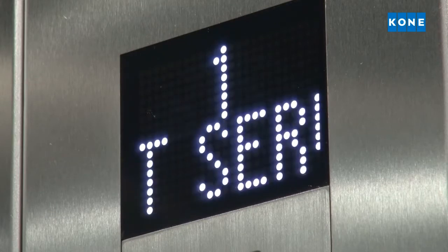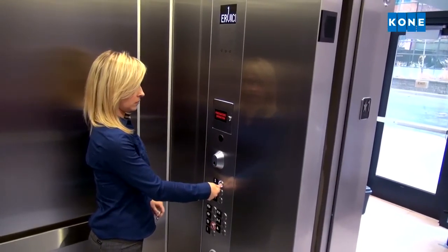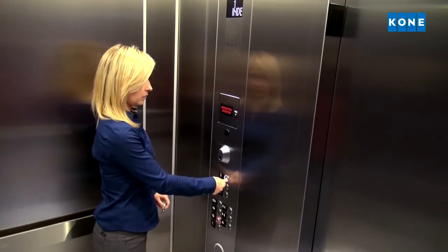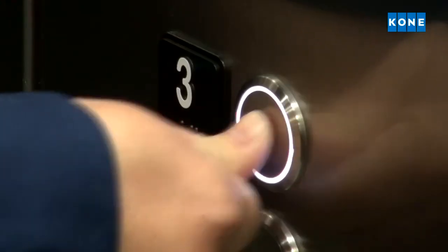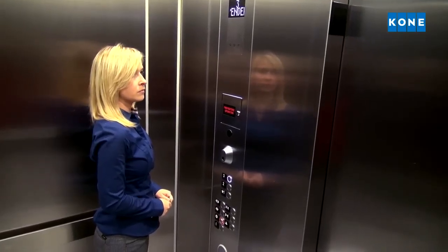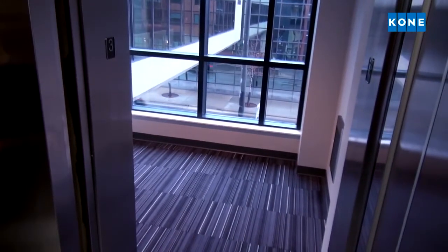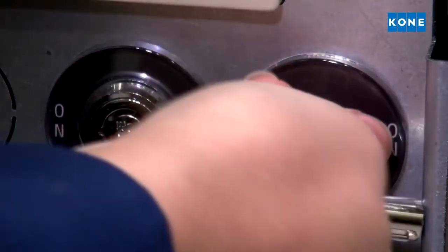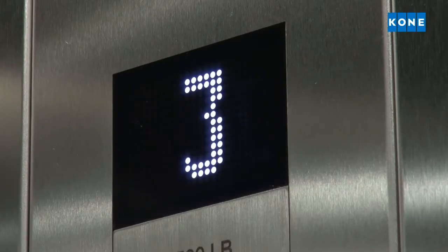With Independent Service activated, moving between floors requires the user to manually depress the desired floor location button until the elevator doors have fully closed and the elevator begins to move. Once the car is in motion, the floor location button can be released. When the desired floor has been reached, the doors will open and stay open until another manual floor move has been completed. The elevator will stay in this operation mode until independent service has been deactivated. The illuminated sign on the car operating panel will no longer be visible, meaning the feature has been properly deactivated.